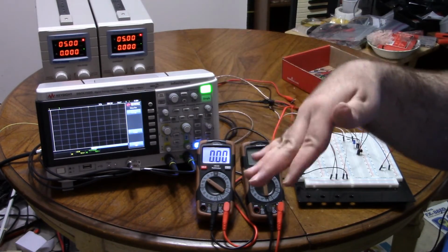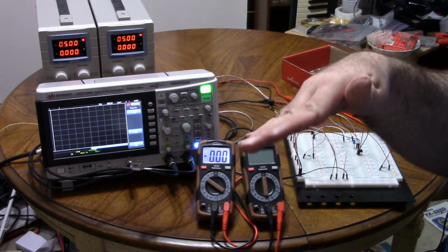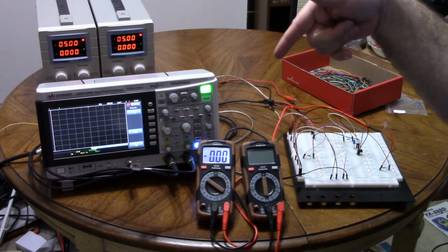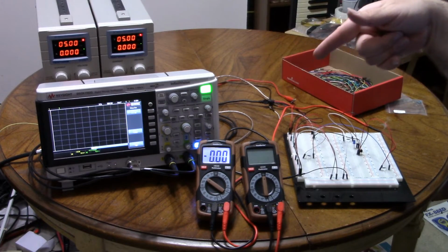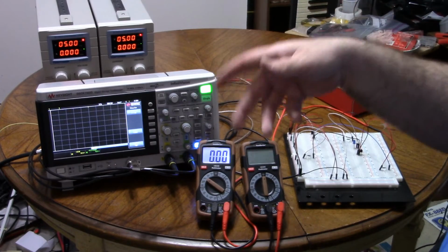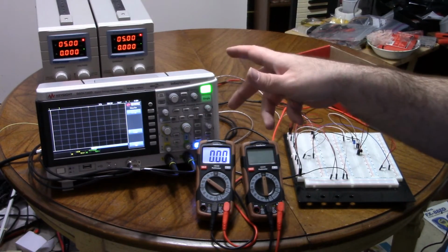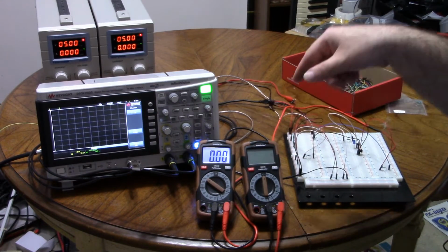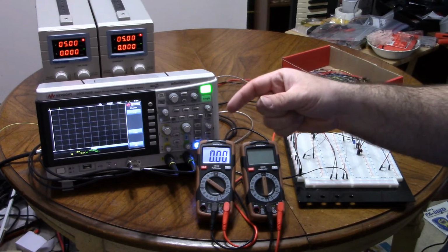The transistor is going to be in its always on state, its active state, just like with the common emitter resistor and the bias, except we're using a negative power supply instead of a voltage divider. And the signal is much more stable because of it. The circuit is much more stable and much more simple at the cost of 2 power supplies. So there's a trade-off there. But this is what I wanted to illustrate, is this is what it means to use 2 power supplies.